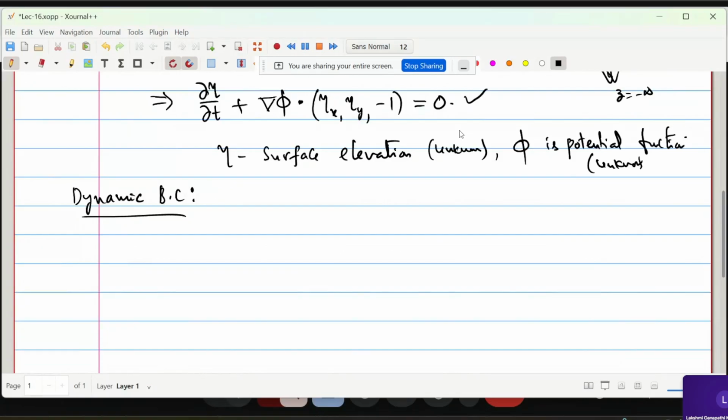I am writing it directly: dou phi by dou t plus modulus of grad phi squared, plus p by rho, where rho is simply a constant or a function of t only. Plus, because of gravitation you have the flow. Otherwise there is no other external force, or no flow as such; the velocity vector is actually 0 without g. So g z equal to a constant.